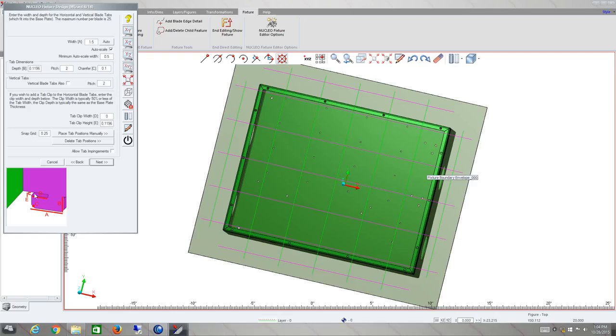If you put a dimension D in there, however, say you put in a 1/2 inch, it'll make an interlocking slot that'll clip into the base plate and lock the whole fixture to the base plate. So it's a way of creating a breakdown fixture where you can put it together, use it for the welding run you're doing, and at the end you can break the fixture down, lay it down flat, so it makes it a kind of collapsible fixture.